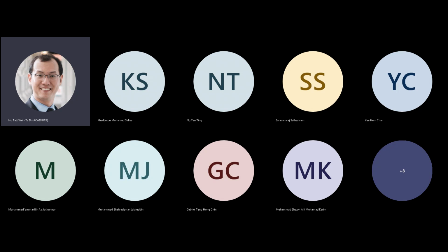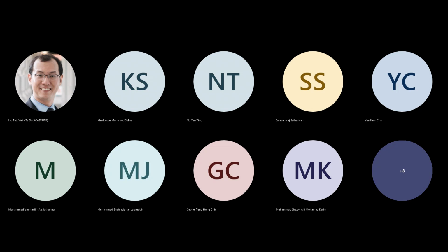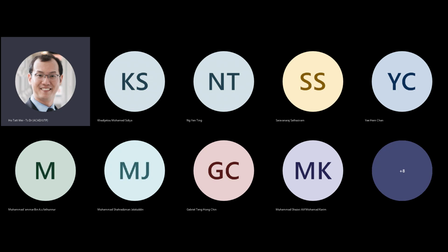So I'm introducing the concept that when we're investigating the delay of a complex circuit, we need to find what is known as the critical path. The critical path is simply investigating all these local blocks of logic. Which path of the combinational logic has the longest delay? Because that combinational logic path will set the maximum clock frequency. And if you can speed that critical path up, you speed up the whole circuit.